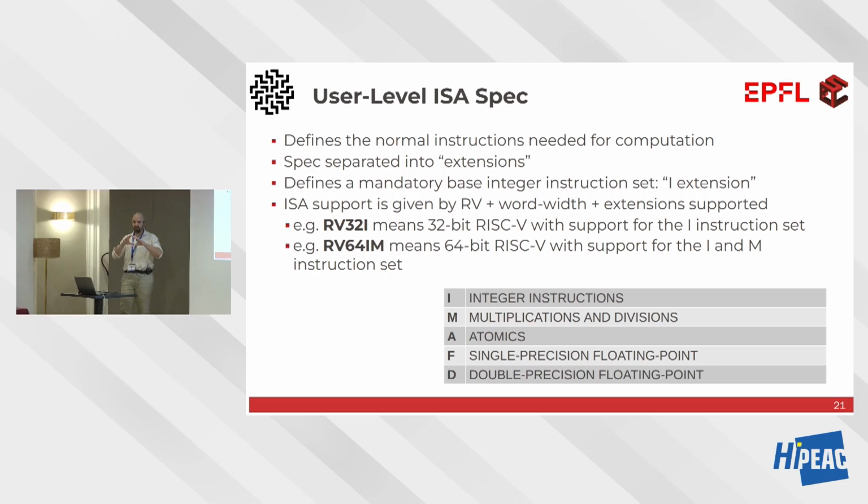What RISC-V does is make mandatory only a subset of instructions, so you can call your CPU a RISC-V CPU if at least it implements the integer extension. That is called I, like the first example here. Then you can decide yourself whether you need a 32-bit machine or a 64-bit machine. How? Maybe as your colleague suggested, by profiling or doing whatever, or maybe you have an application that is already tested with 64, so you need 64.